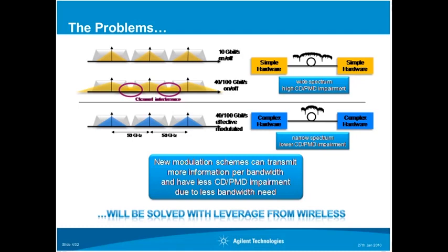If you look at that, it's actually something very common. The wireless people have been doing this for ages, and if we think back 10, 15 years ago, we used to transmit 56 kilobit over a 3 kilohertz phone channel. So that is exactly what's happening now in the optics, and it's actually quite thrilling to see that these kinds of advanced modulation schemes are finally arriving in the optics. So compressing the bandwidth of a channel is nothing really new. You rather talk about symbol rate now instead of bit rate.